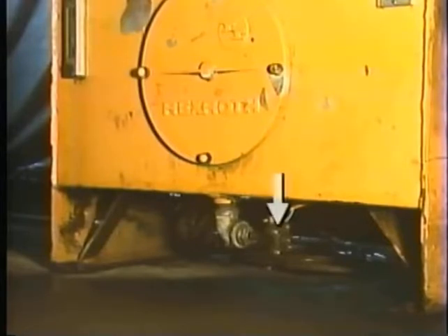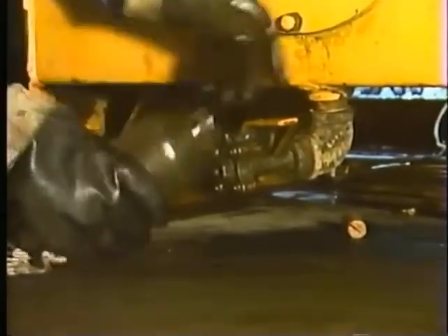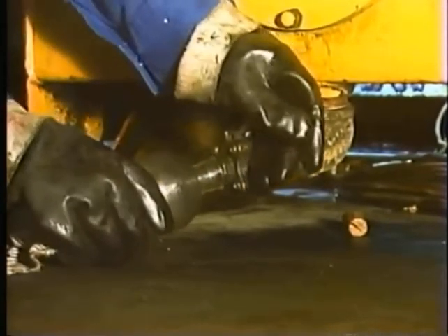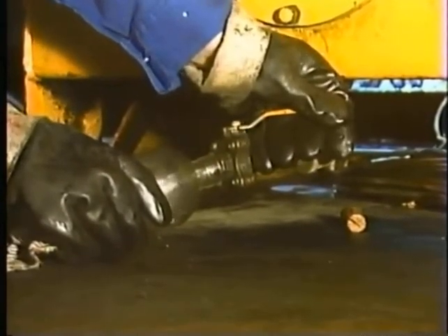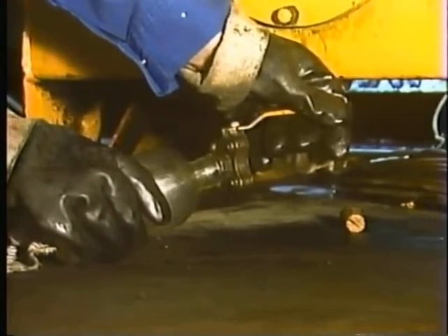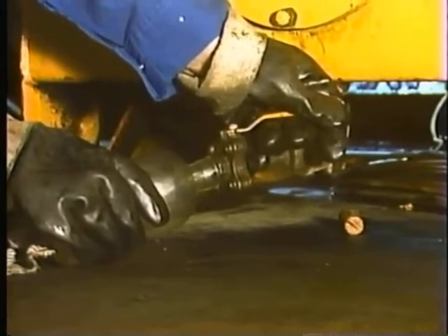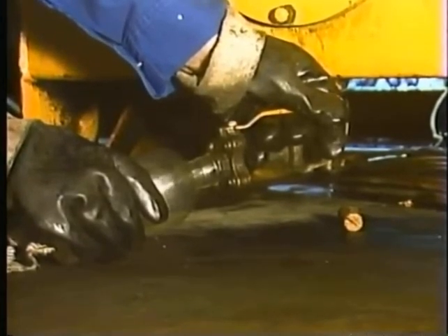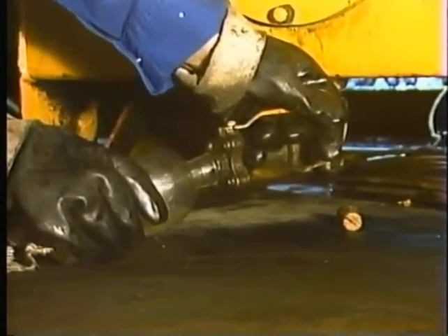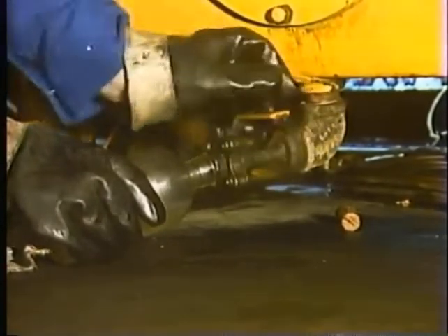The bottom of this reservoir has a valve at the lowest point where a sample can be taken. The fluid sample this operator is taking will be sent to a lab for testing. The tests can determine contamination levels and content, which can give some clues to the causes of any contamination. When appropriate, the valve can be opened to remove a portion of the fluid from the reservoir to help remove solid contaminants that have settled to the bottom.